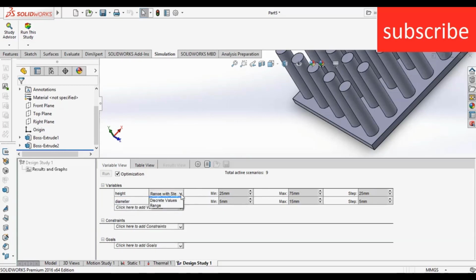Now here you see range with step, discrete value and range. Here I am selecting range with step. A question will arise in your mind, what is range with step? So let me tell you. In range with step, you type a minimum value and a maximum value, and you type a step of 25 mm, whatever you want. Remember, the lower the step value, the better the result you will get.